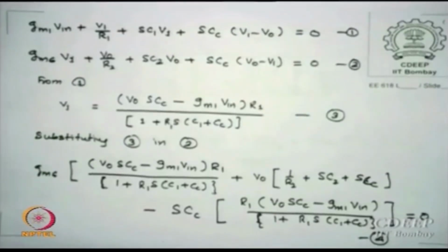Why are we doing all this? I want to design an OPAMP, so I am trying to correlate the gain function, the slew rate function, power, everything with whatever spec I have. So I am trying to get the relations, and what is the major relation I will get from this? The poles and the zeros, because they are going to decide in some way my GMs, because a pole is essentially GM by C. That means GM is now decided not just by a factor but also by the poles available to you, and that is why we are interested in getting those expressions. Is that correct?